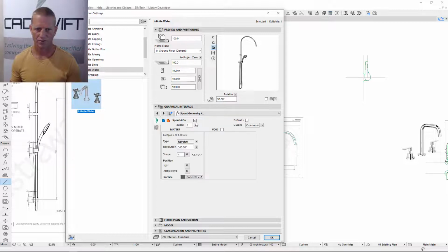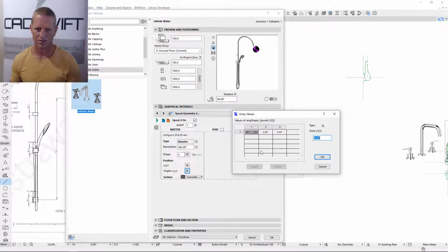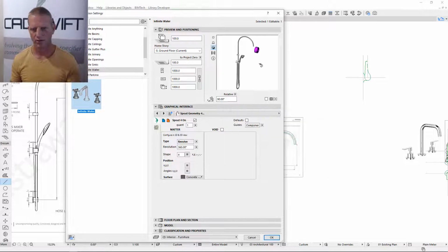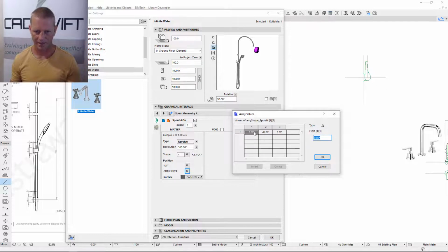Oops, better turn it on first. Okay, that's it there. So that's pretty much where we want it. Let's now rotate this. Revolve travels along the x-axis, so you need to rotate the y-axis minus 90. Turn it up. And we've got an x-axis of 90, so we need to combat that with a minus 90 as well.